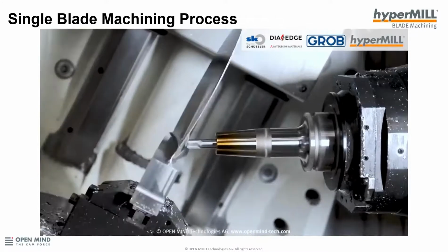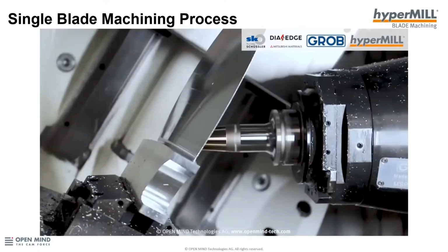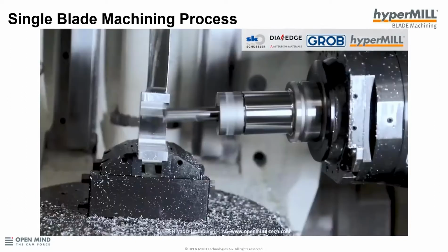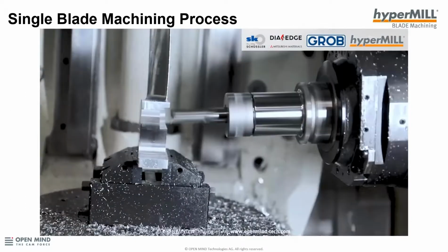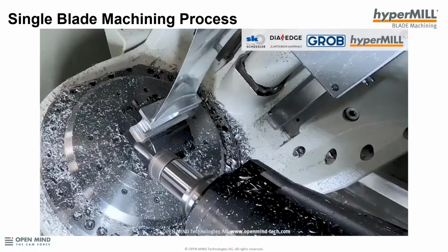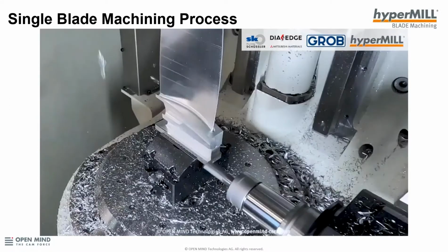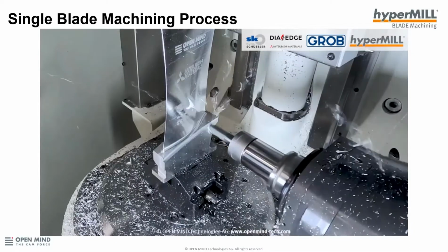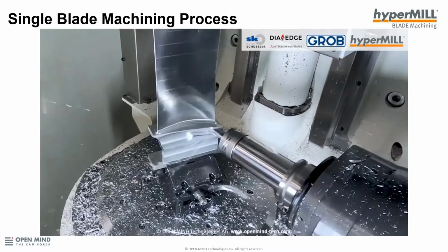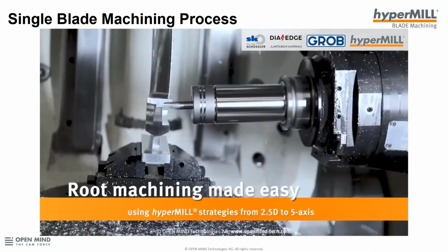And this segmental blade machining process provides stability to these thin blade structures. And of course, again, the same barrel tool is used for blending and transition towards the platform. So quite easy to machine even the roots and the fir tree with simultaneous machining as well.